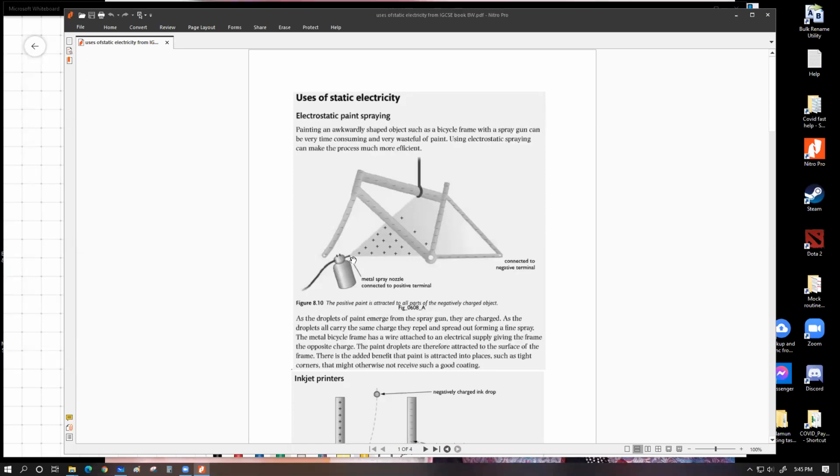If you are not using electrostatic spray painting, the nozzle cone size would have been much smaller. So these are the two advantages of electrostatic spray painting. We can get more uniform thickness and less wastage, and the paint droplets coming out of the nozzle are going to spread out more because of the repulsion forces between them. Practically, you are asked about the advantages of electrostatic spray painting and also the underlying physics-based principle, that is, why this is better compared to regular spray painting in the first place. So that's all you have to say.